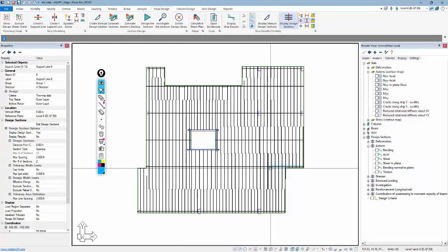Where we ended up last time, we talked about meeting the serviceability requirements of the slab, and that's necessary in order to determine what post-tensioning we need, what effective forces we have in our strands, what the position of the strands are with respect to not only the depth of the slab but also in plane. All of those affect the strength calculations in the program. So before we go into determining what the reinforcement requirements are for not only service minimum reinforcement but strength, we have to get a good feel, and we have to kind of hone in on what the post-tensioning is going to be in the slab.